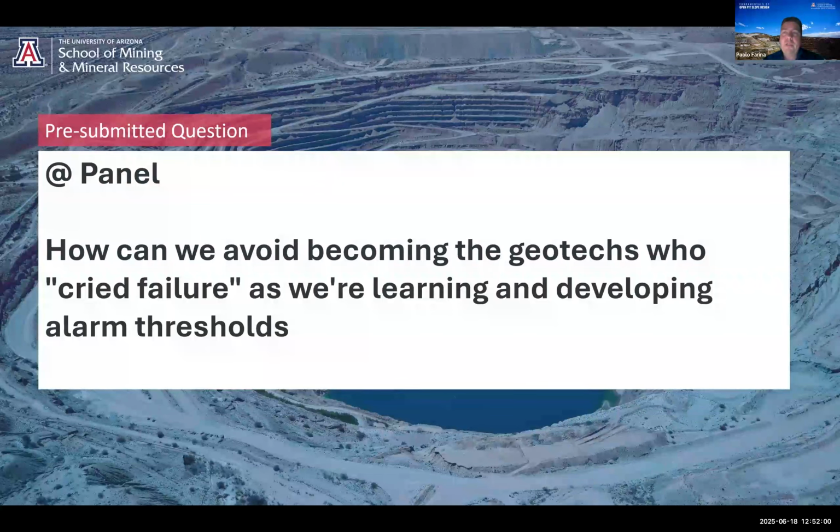And what is important is to provide some basic elements for them to start to build on in the first, let's say, period they are using. But they have questions to be addressed. For example, I'm dealing with a client who has an instability detected by an extensometer. So they started to use a radar right now, but they are reprofiling the slope. So they closed the pit for the time being when the radar was reaching the site. Now the radar is on site, so someone has to take the responsibility to say, okay, what are the thresholds?